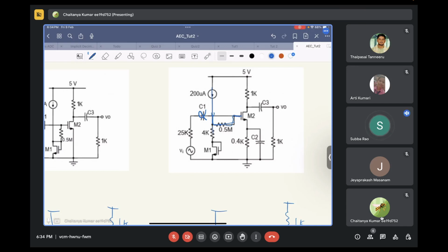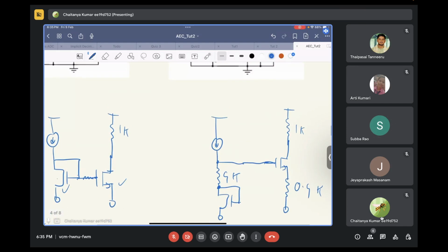And if nothing is flowing through a resistor, then there is no voltage drop across that resistor, correct? So any value of resistance in this path, as long as it does not become equivalent to the gate resistance, which here we have assumed infinite, does not matter at all as far as your DC circuit is concerned.